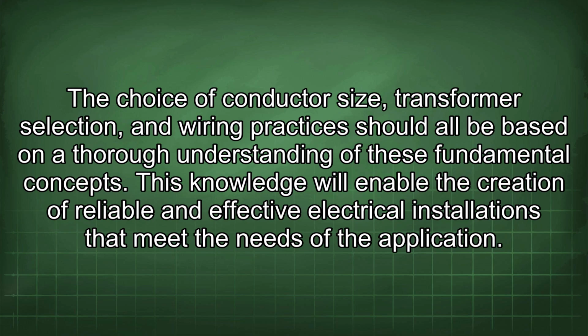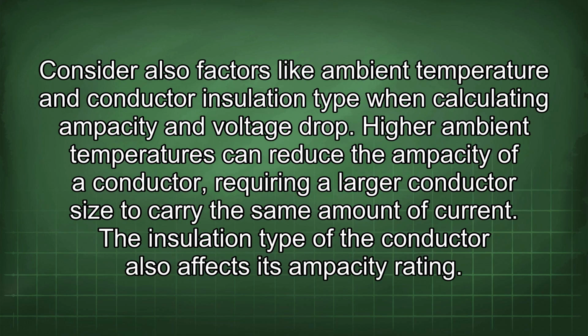The choice of conductor size, transformer selection, and wiring practices should all be based on a thorough understanding of these fundamental concepts. This knowledge will enable the creation of reliable and effective electrical installations that meet the needs of the application. Consider also factors like ambient temperature and conductor insulation type when calculating ampacity and voltage drop.